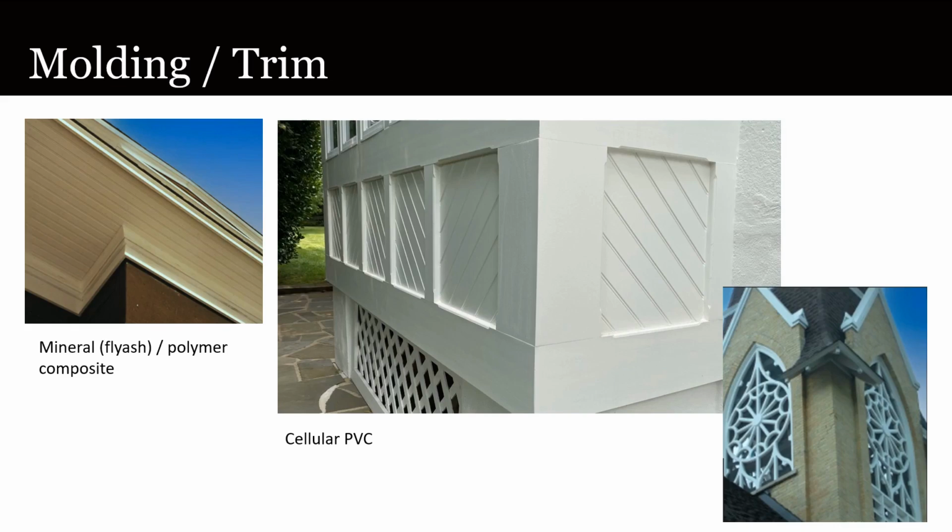Much historic trim was not designed to shed water the way most wood siding does, making it a feature frequently prone to decay. Moreover, trim typically involves a lot of joints with material oriented in different directions. Understanding the relative movement characteristics of the chosen material is critical to its successful use. Most of the substitute materials suitable for use as trim, unlike wood, are isotropic, and regardless of whether their expansion and contraction is driven primarily by heat or moisture, they will move proportionate to their dimensions, equally in all directions.